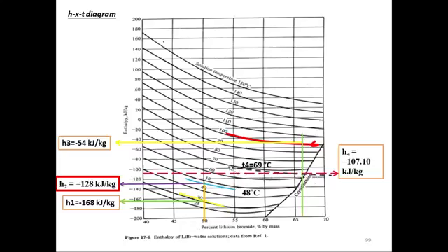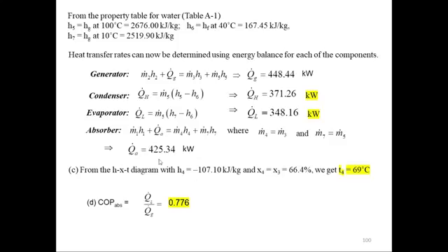So you have to draw a parallel line between 70 degrees centigrade solution temperature and 60 degrees centigrade solution temperature. So by looking at the 107 value here, you try as close as possible to draw this line. We should pass from this point which is crossing this green line and the brown line. So that temperature, if you look it up, it will be 69 degrees. It is very close to 70 degrees. So that's the temperature value we have taken. Let's go see it. So T4 is 69 degrees. That's how this 69 degree temperature has been figured out.